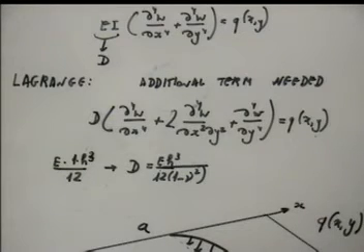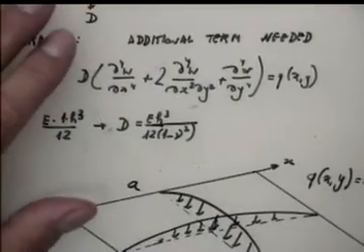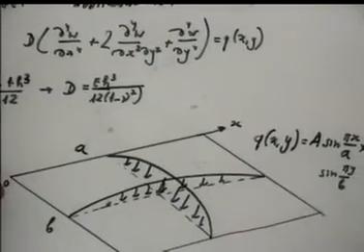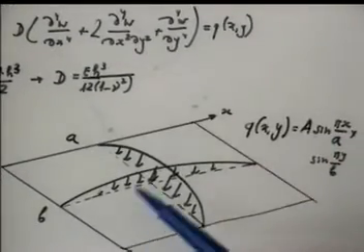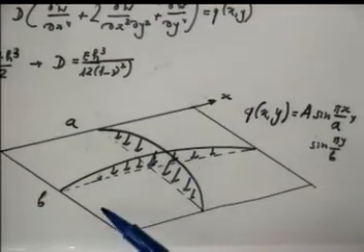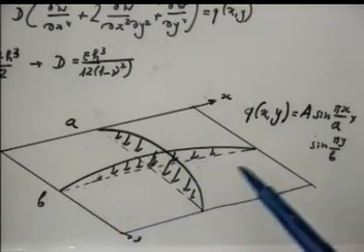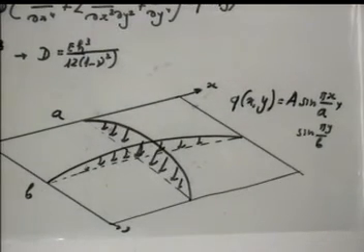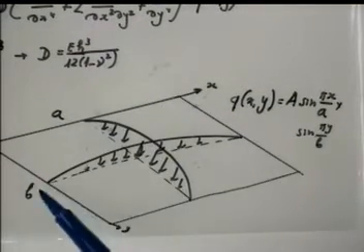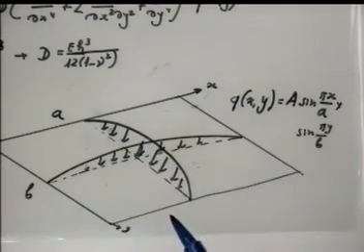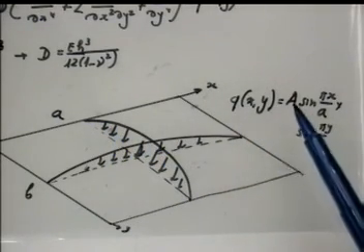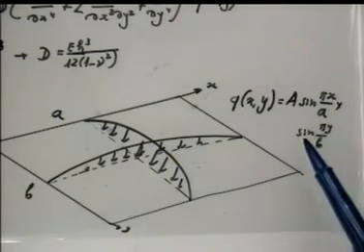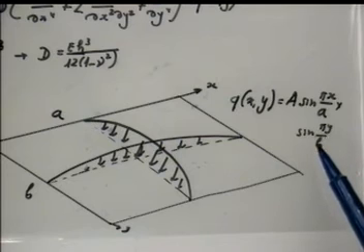Let us first not obtain this equation, say, rigorously, but solve some problems. Imagine for 1 second that the load is given like this. Look, this load is actually also here, everywhere. That is a distributed load. And I just showed maxima. So to say, q(x,y) equals q0 sine pi x over a times sine pi y over b.